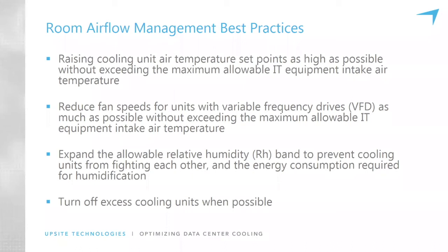If variable frequency drives are not installed on cooling units and fan speeds can't be reduced, then turning off cooling units is possible once airflow management has been improved. This is one of my favorite things to do, is turn off cooling units. I've turned off a lot of cooling units in rooms, and very often conditions actually improve. Airflow management is improved because bypass airflow is reduced, cooling units can sense the load that's in the room, and conditions get better with fewer cooling units running.